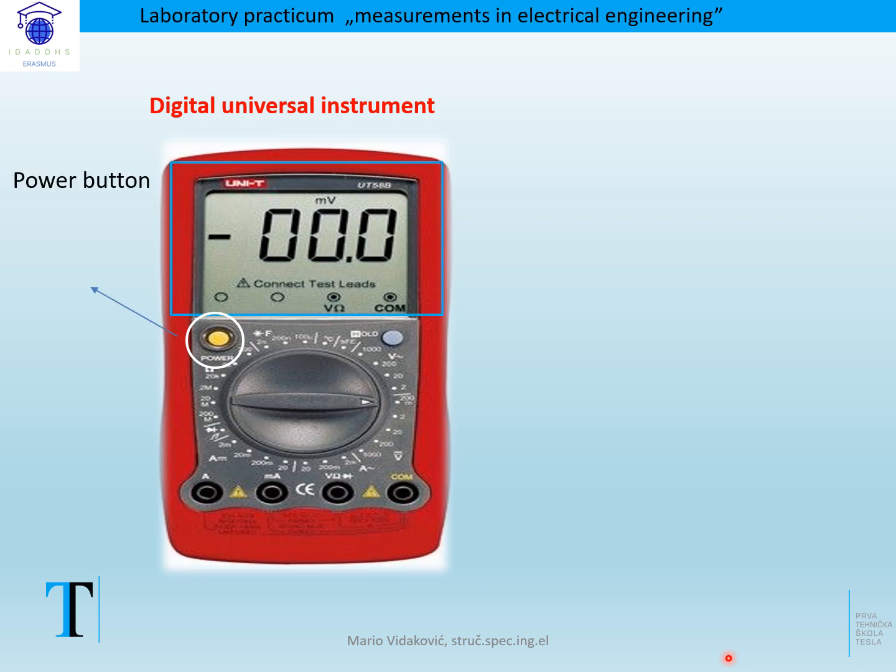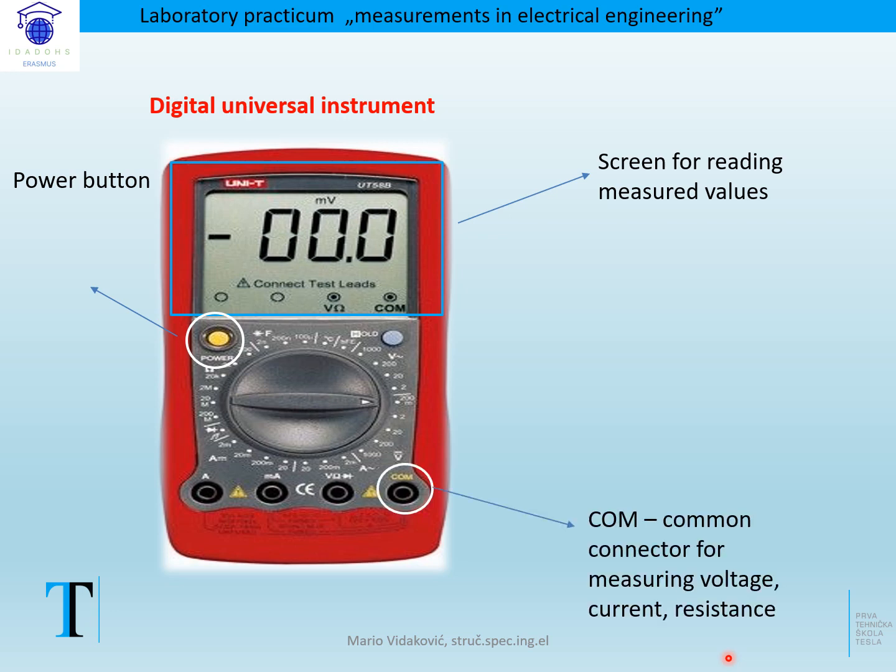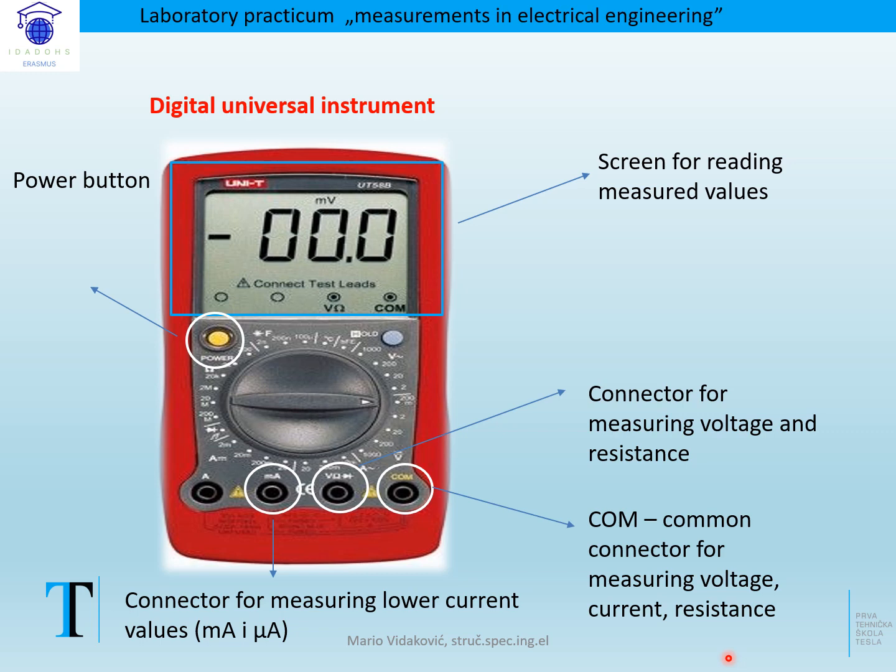Power button to turn the instrument on or off, digital screen for reading measured values, common connector for measuring voltage, current or resistance, connector for measuring voltage and resistance, mA connector for measuring lower current values in milliamperes and microamperes, ampere connector for measuring higher nominal currents in amperes.